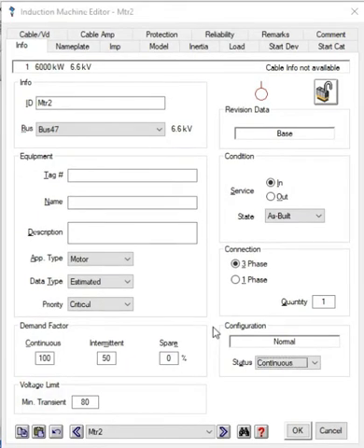So now let's come to the point of what sort of parameters you need to ask from the motor vendor, which are required as input in ETAP to check its dynamic behavior. First you have to define the duty cycle, which means whether you want to run in a continuous mode, in an intermittent mode, or as a spare. From here you can choose the option.